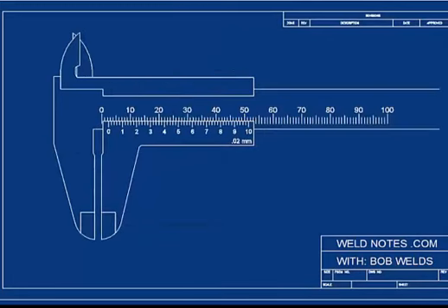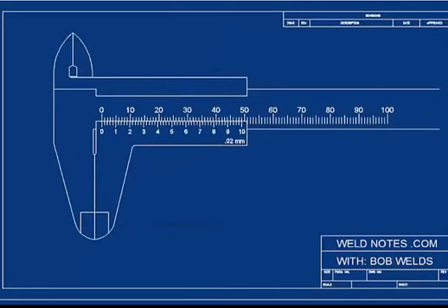You see, when the calipers are fully closed, measuring 0 width, you can see the places where you can take measurements. These surfaces are where the two parts of the calipers line up. You'll also notice that there are gaps in a couple of places on the calipers. These are not places to take measurements, so don't mess up by putting something in one of those gaps.